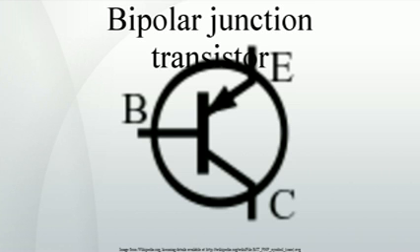Both types of BJT function by letting a small current input to the base control an amplified output from the collector. The result is that the transistor makes a good switch that is controlled by its base input. The BJT also makes a good amplifier, since it can multiply a weak input signal to about 100 times its original strength. Networks of transistors are used to make powerful amplifiers with many different applications. In the discussion below, we focus on the NPN bipolar transistor.